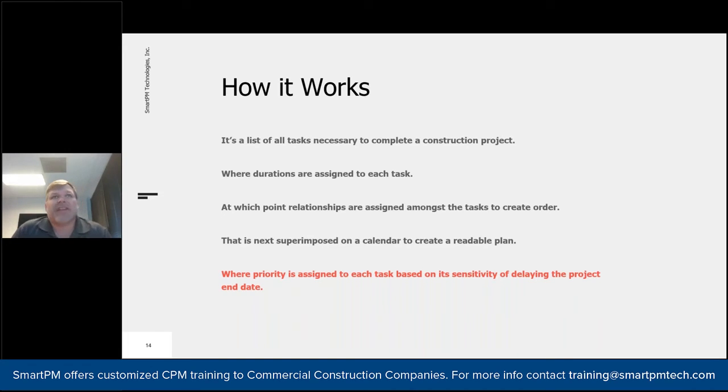And so you assign a duration to that. Say I want to put drywall up on the 4th floor, and that's an activity that I have a trade contractor working on, and I know it's in a specific area. I have to assign some time. Things don't happen immediately, and there's usually a period of time necessary that we estimate at the beginning. That could be accurate or could be wrong, but in general, we want to come up with a duration that we think makes sense. I tend to think coming up with a risk-adjusted duration is a little bit better than a best case scenario type duration. But nonetheless, you have a list of things that need to get done, and each one takes time, and you need to assign that time.